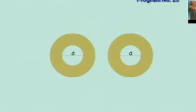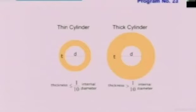And if the thickness of the cylinder is more than 10% of the diameter, then we call it a thick cylinder. Please understand, this 10% is just an approximate figure. Most of us may not agree with respect to 10%. Some say it is 7%, some even say up to 20%. But basically, for us, the comparison is the thickness to the diameter. So, if the thickness is relatively small when compared to the diameter, you can say that the cylinder is thin, otherwise it is thick.